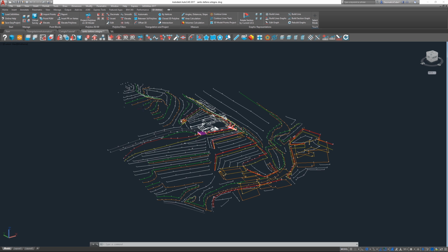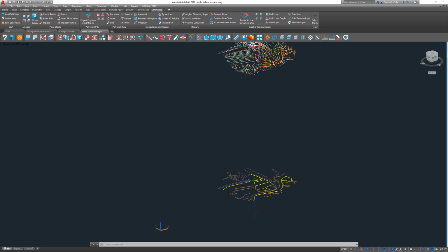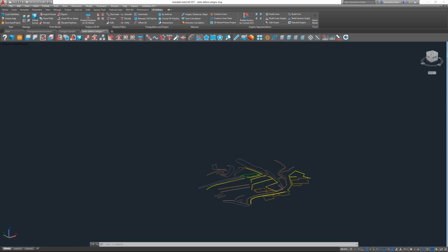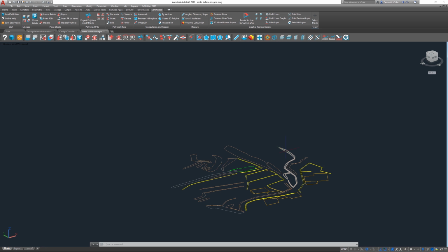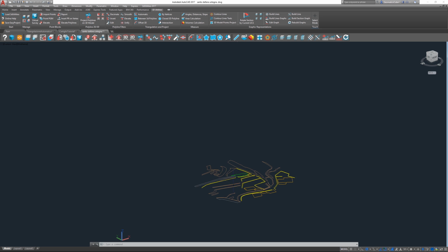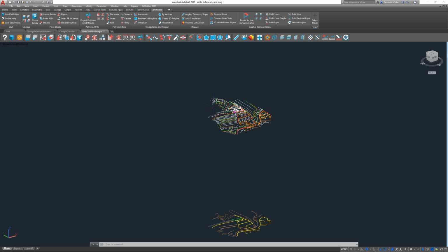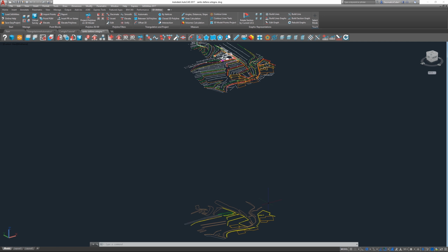It's really useful before you launch the automatic triangulation to have also these closed 2D polylines. So these are created specifically for the automatic segmentation of the model. So this way, when you launch the command, you will automatically segment the various parts of the model, so to speak. It's really easy to create those.